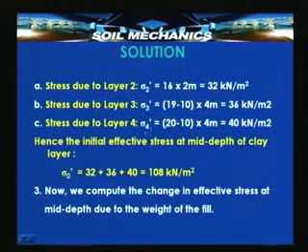What shall be the stresses? Layer 2 has a thickness of 2 meters and its unit weight, moist unit weight, has been given as 16 kilonewtons per meter cube, and therefore, the corresponding stress at mid depth of the clay layer due to this overlying layer of wet sand is 16 into 2 equal to 32 kilonewton per meter square.